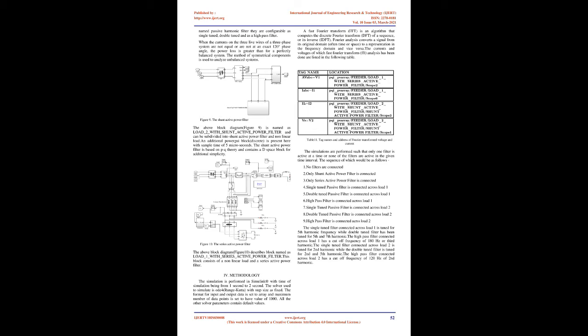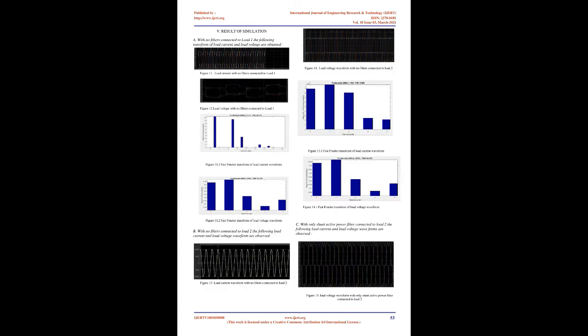A 100 kW PV array is connected to a 25 kV grid via a DC-DC boost converter and a 3-phase 3-level voltage source converter, VSC. Maximum power point tracking, MPPT, is implemented in the boost converter by means of a Simulink model using the incremental conductance and integral regulator technique. Another example, the average model, uses average models for the DC-DC and VSC converters. In this average model, the MPPT controller is based on the perturb and observe technique.